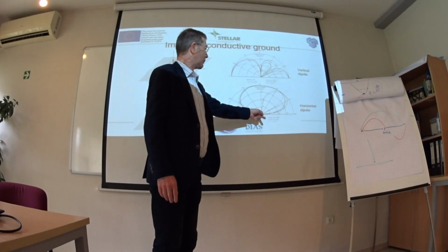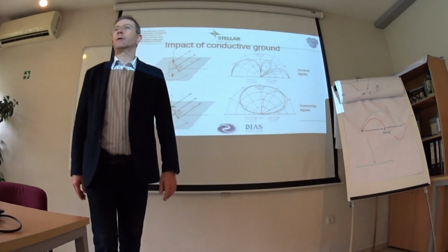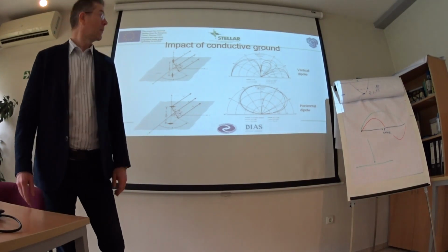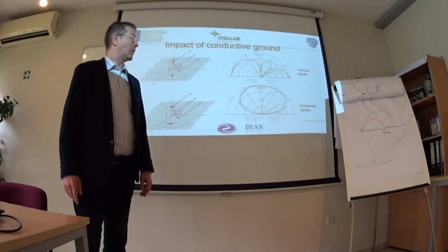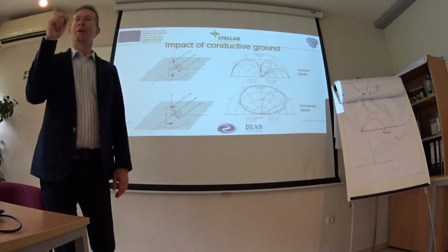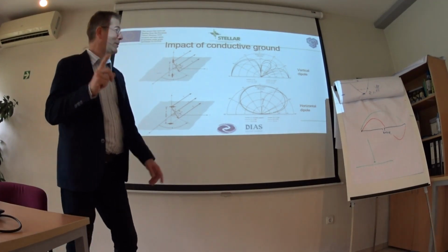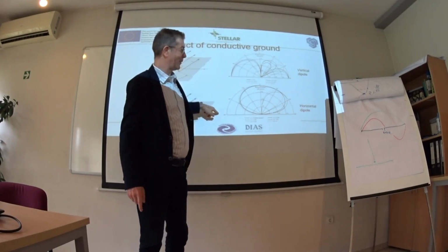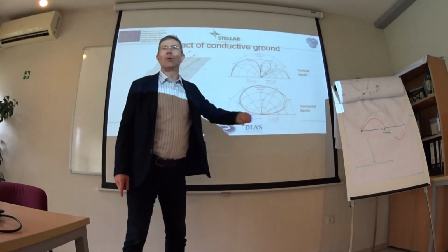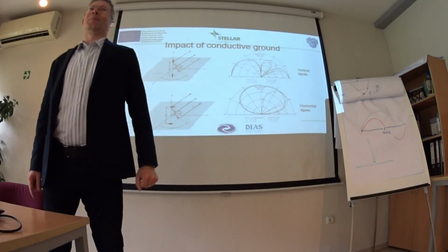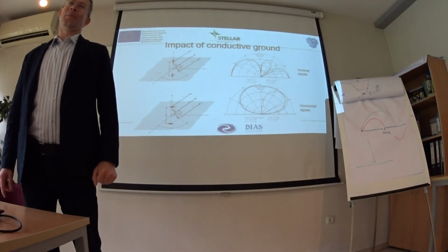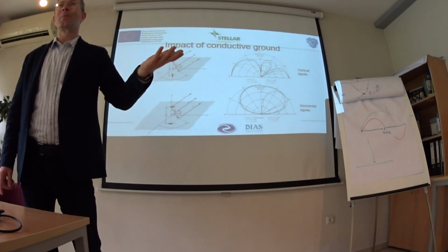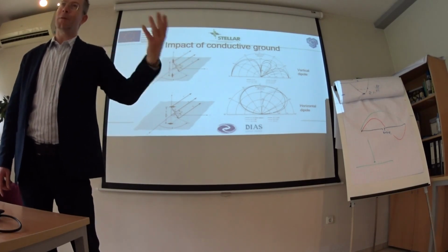And horizontal dipoles never work very well over the ground, with one exception. In our case, for radio astronomy, since the target is above, not at ground level, this concept works. So in the general case, if we need it for broadcast, a horizontal dipole is a bad thing.